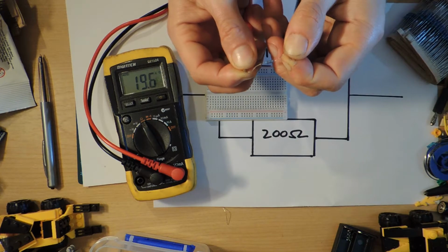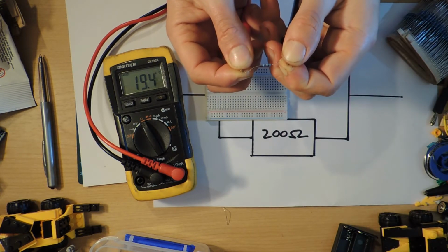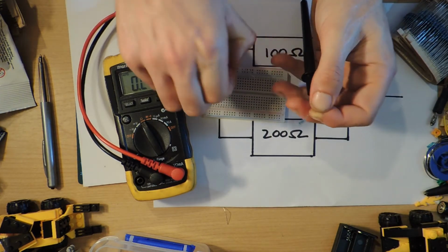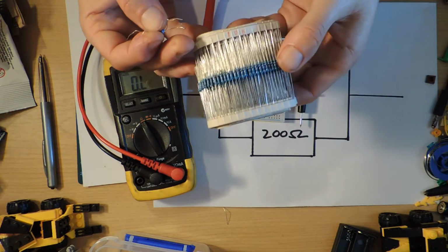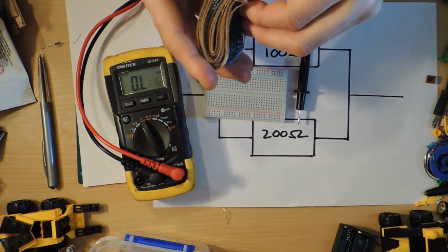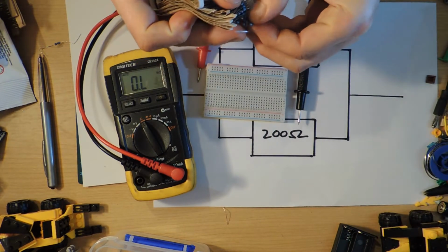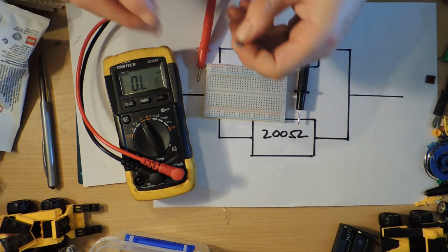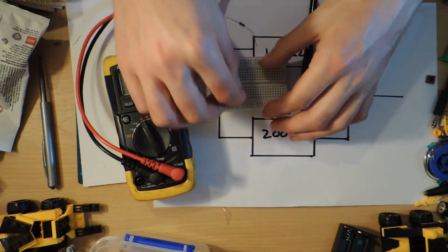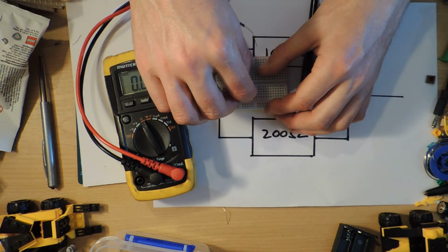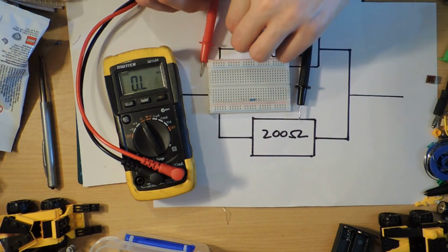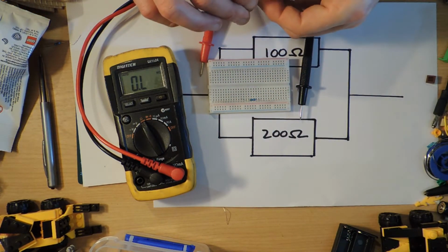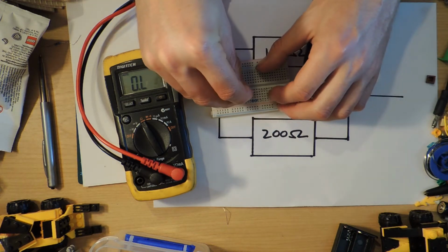Oh, well, look at that. Okay, so I picked up the wrong box. Really? These were all 10K. Okay, so actually that did work. I thought they were both 10K, and so I'm a bit perplexed as to why it says that it's still 10K with two of them, but in fact they are 20K. And so when I put them in parallel, they come out at 10K, which is funny when you think about it. So let's do this again, and we'll test the resistance.